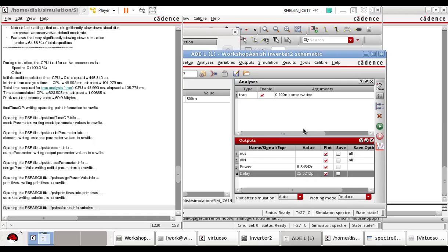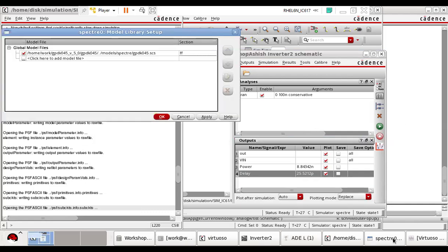It is consuming less power, but I'm repeating, you cannot do this on your IC by yourself. These are environment-based conditions, or by the life or by the time. If this kind of condition comes in, then what will be the extreme results? That is what we see in the process corner analysis. It is the extreme result if my NMOS and PMOS both get faster. Now I'll see some other results. Remember the delay was 25.52 when both get faster.